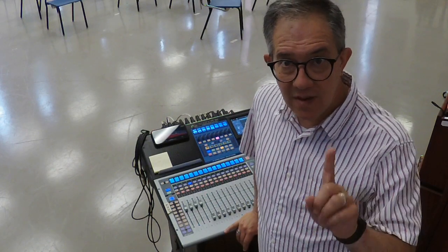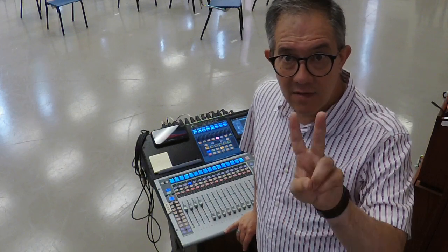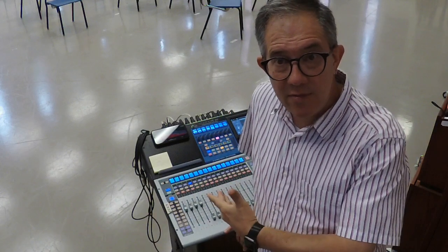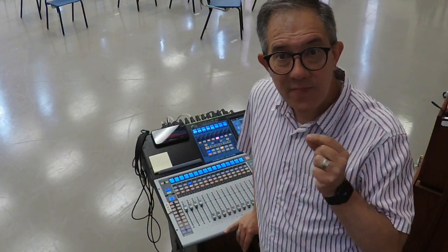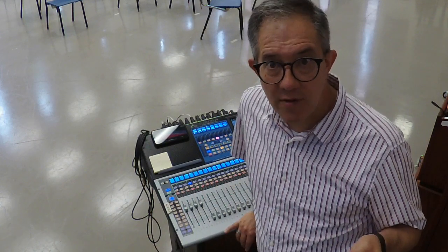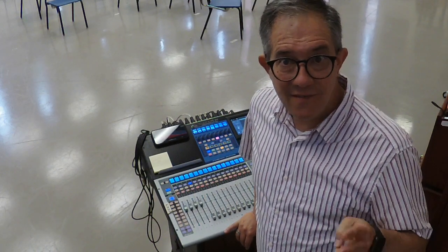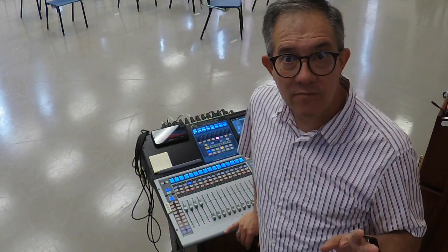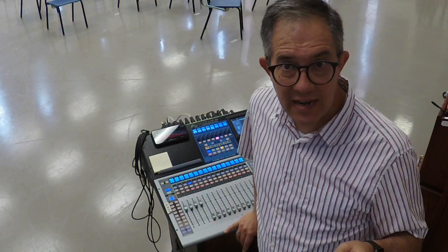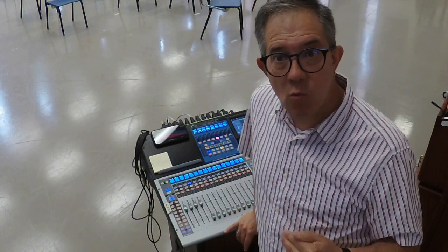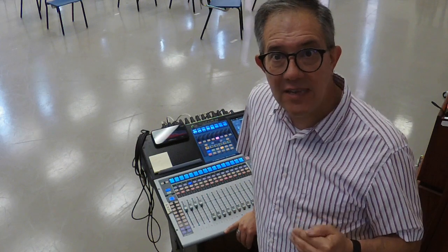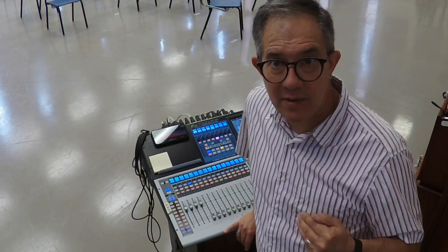So all you need is the ability to make it feedback, an RTA to tell you what frequency it is, which might be built into your console, or you may be able to download a free app for your phone, and the ability to actually apply some EQ to the output of your console. If you can do those three things, fairly simple, you've got the ability to really tame what's going on from a standpoint of feedback in your facility. And you only have to do this once. Once you've set that frequency and cut it, it's going to tend to be much better behaved.